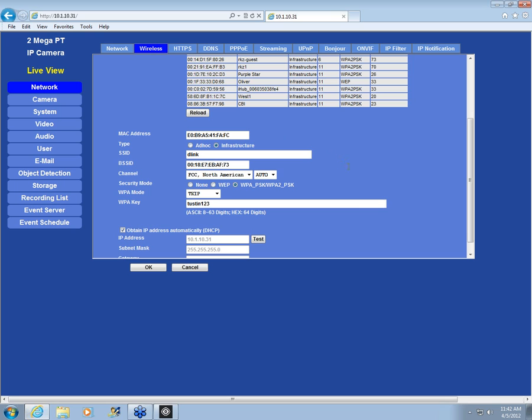Here's a question on wireless. Since you defined it as primarily inside, how far can you run the cameras in a building, let's say a 50,000 square foot building, before you have degradation of the signal? Well, wireless is so unpredictable, but theoretically it is 300 feet line of sight. Line of sight could mean anything, so that's in the ideal situation. But you can always put up repeaters all over the building to enhance your signal.